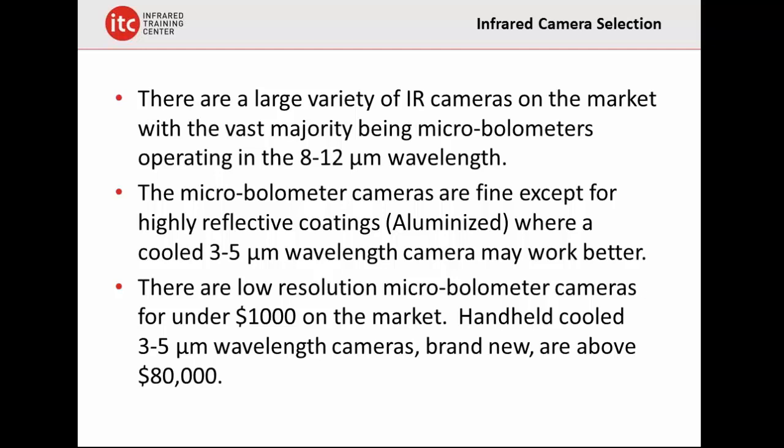Well, I've seen a couple thermographers with an old Thermacam 290, 390. If you can find the PM 290, 390 cameras operating in the midwave, with the platinum silicide detectors, absolutely, they would definitely work on a roof like that. Old Agema 470 cameras, the big old camcorder type cameras, they would work. Yeah, we used those on those roofs as well.